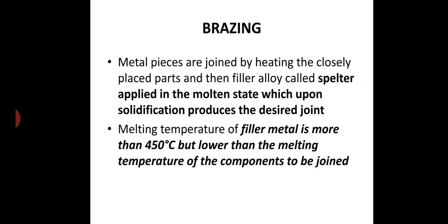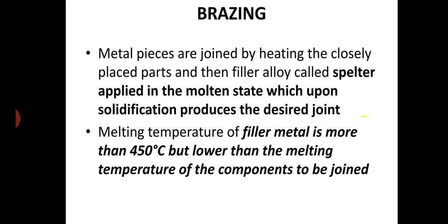Coming to brazing, we actually generate more temperature than in soldering. So the filler material is different. It's called a spelter, which is an alloy of copper and zinc. The melting temperature of the filler material is hence more than 450 degrees Celsius.